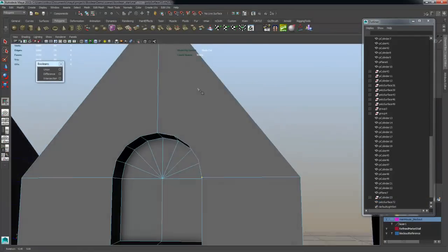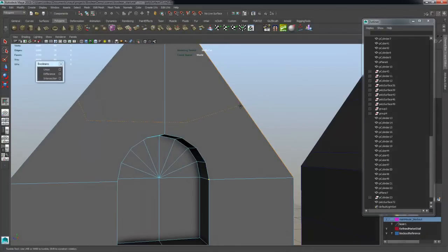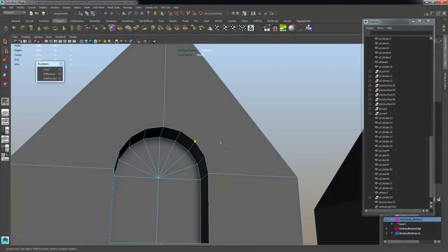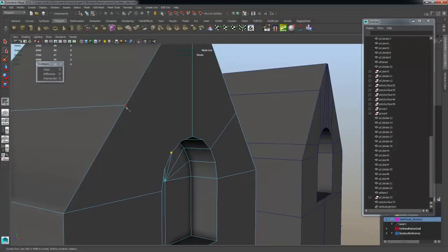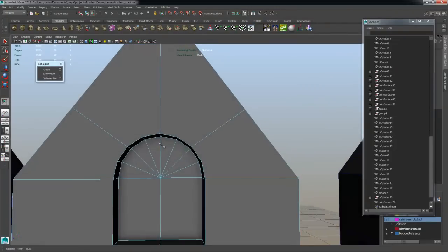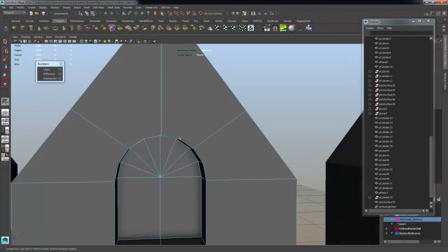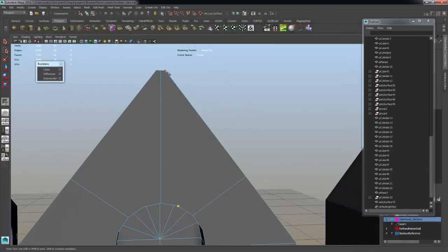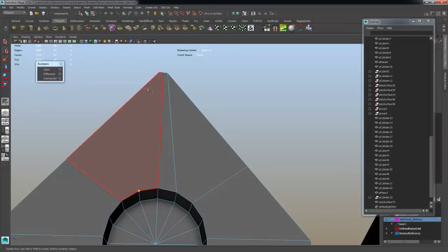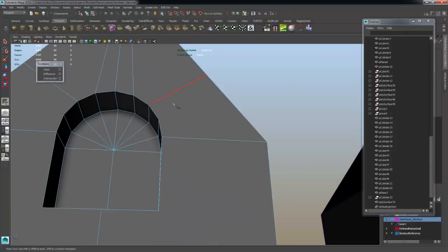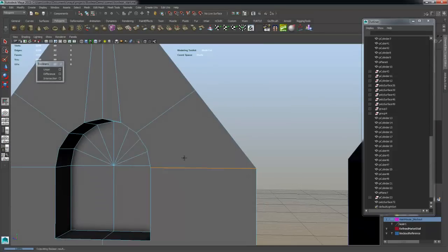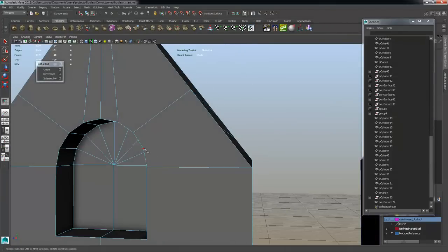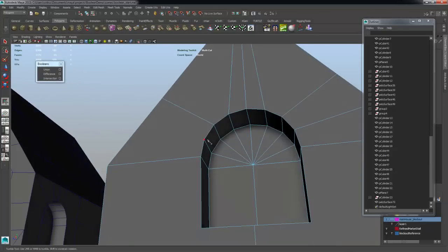And I'm going to use the multi-cut holding down. We've got 1, 2, and 3, so I'm going to divide this along the 50% mark, which is around there. I'm going to go ahead and connect this one to the outside. I'm literally just clicking, pressing enter, and I can go ahead and do the same thing there. So I'm going to go from there all the way to that upper vertex, same thing over there, upper vertex, and then finally these go around again the 50% mark maybe. It's not 50%. There we go. Connect that to the outside, and finally